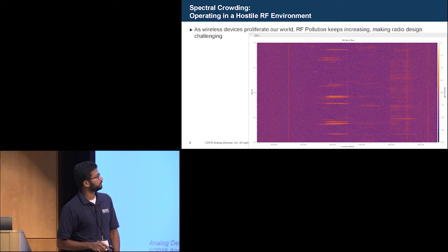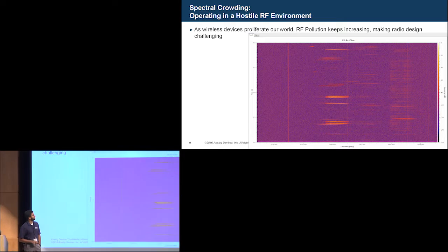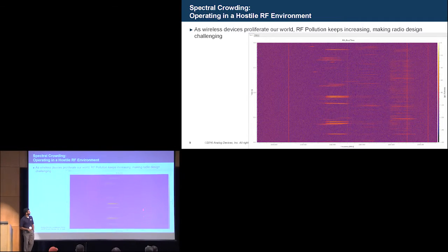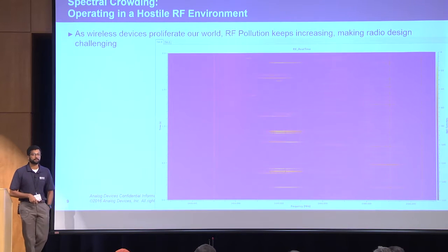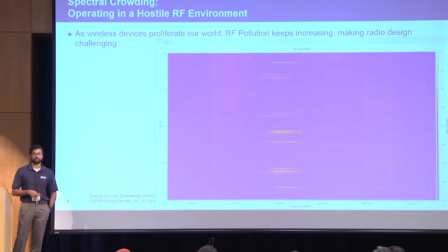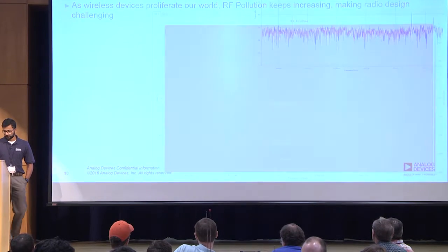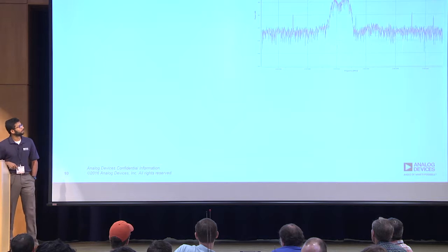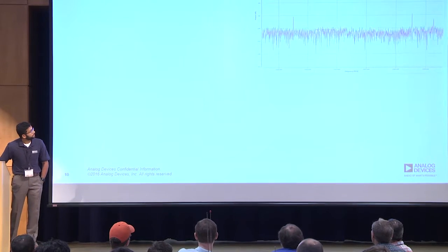Let's say it's a narrowband FM modulation channel right there, but I have interferers coming in all over me all the time. If I don't react to it, if my AGC doesn't get to it fast enough, then what I'm losing is bits, actual data bits. Just a small GIF to show you what that looks like in real time, with my poor GIF skills.